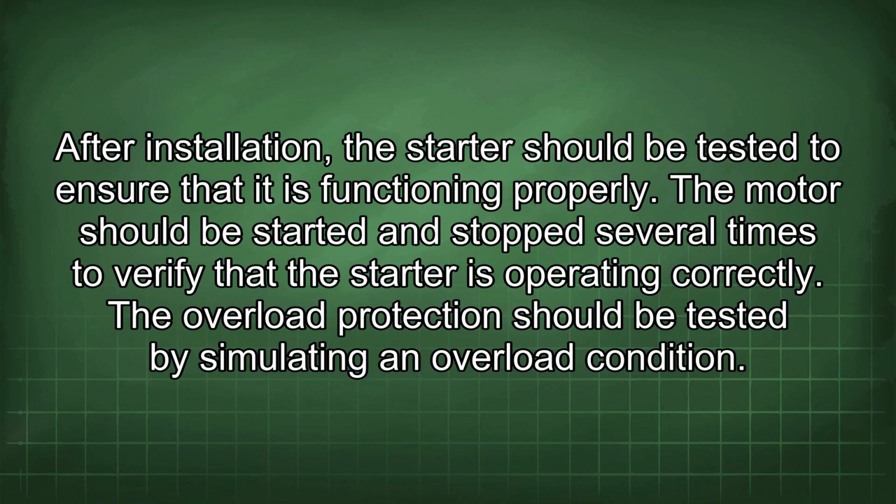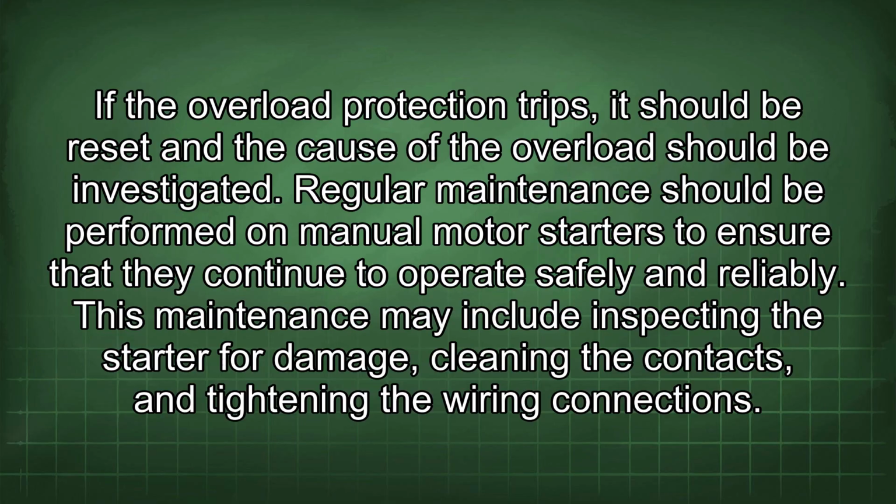After installation, the starter should be tested to ensure that it is functioning properly. The motor should be started and stopped several times to verify that the starter is operating correctly. The overload protection should be tested by simulating an overload condition. If the overload protection trips, it should be reset and the cause of the overload should be investigated.